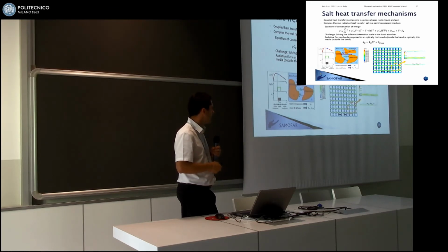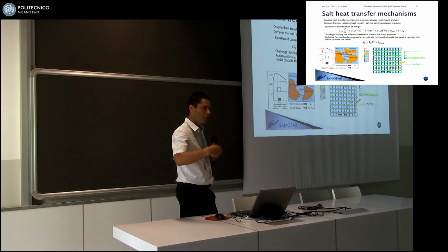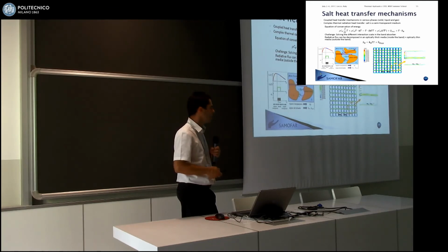And inside the band, where the fluid is absorbing all the heat radiation, basically what will happen is that the thermal conductivity of the fluid will be increased by the presence of this band. So we have been doing also simulation, like this is a porous medium made by cylinders, and trying to study how radiative heat transfer will change things in the salt.